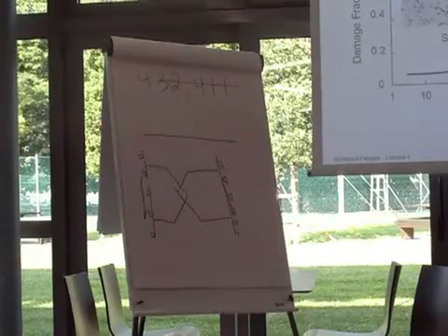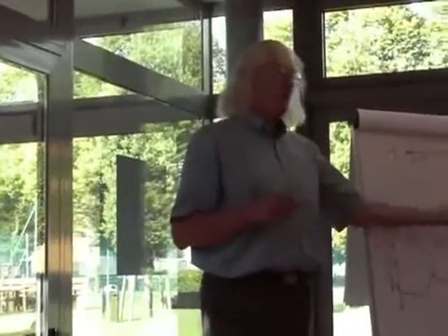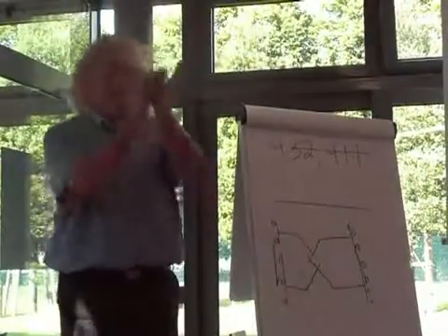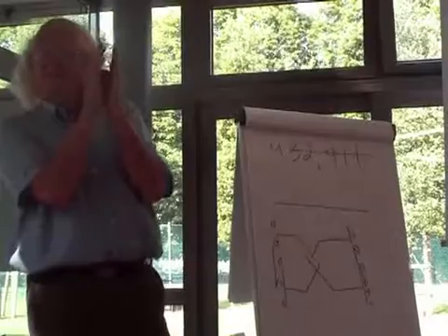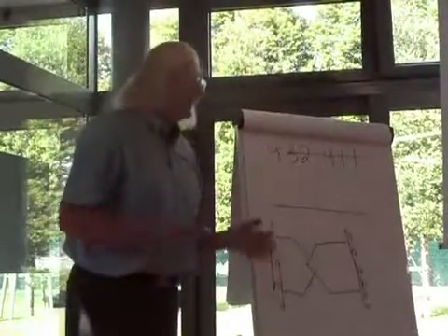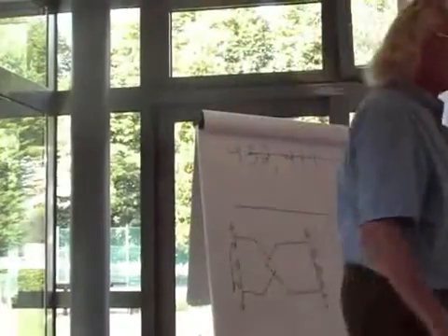So the only way to grow a shear crack is to try to do it in a tube. But even in a tube, they try to turn and grow into tension. That's the difficulty of getting a long shear crack. A short one is easy. If I want a shear crack that's 0.5 millimeter long, that's pretty easy. Getting a shear crack to grow in shear that's 10 millimeters long is really, really hard.